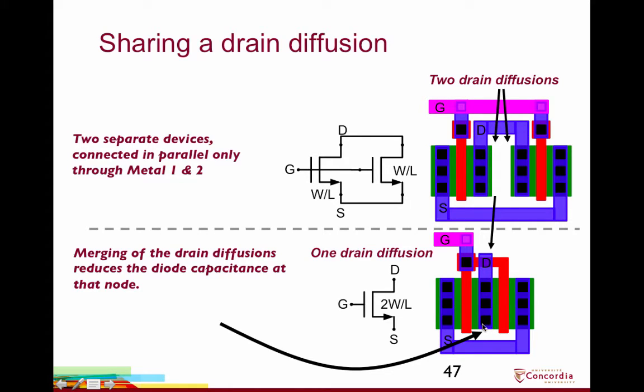So in general, we're going to split transistors into fingers. If we split a large transistor into a large number of fingers, we'll end up sharing source diffusions as well. So in general, we're going to have one more source diffusion than drain diffusions when we split a transistor into an even number of fingers, assuming that we assign the drain node to the node with fewer diffusions.